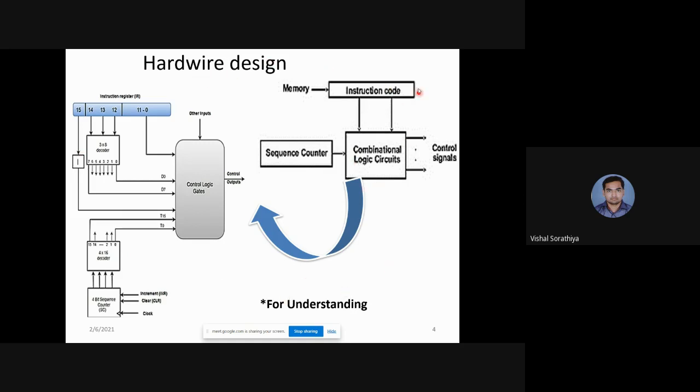From that, there are some blocks which generate the control signals, and this is fixed according to the 0 to 11 bits, and according to bits 12, 13, 14 and their variants, some set of instructions is fixed. For example, if they have fixed that block to do only ANDing and complement of the logic function, you can say you have only OR, AND, and NOT gates available.